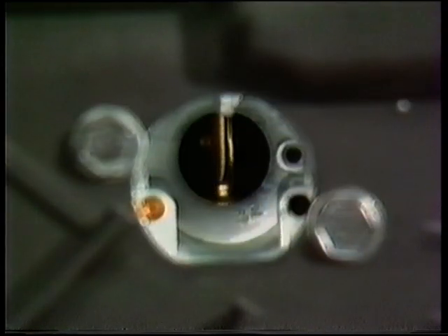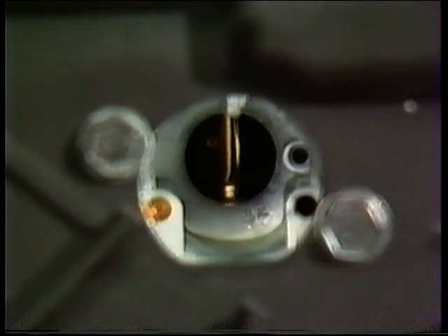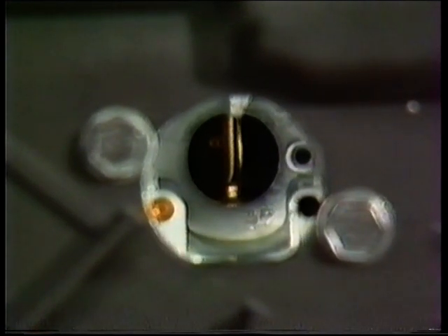Remove the air cleaner assembly and look directly into the throat of the carburetor. You should see a pulse of fuel each time the primer bulb is depressed. Fortunately, there's an easy and accurate way to check fuel delivery to the combustion chamber once you've verified the choke position or primer operation. Turn to the humble spark plug.